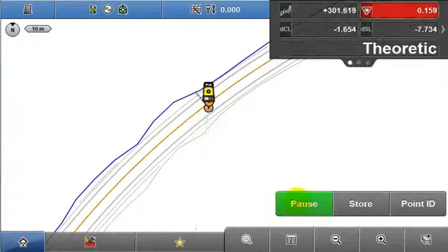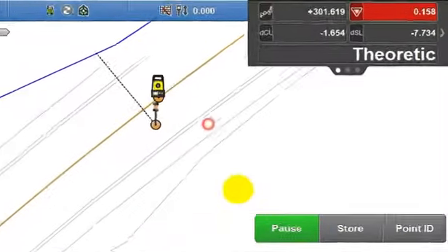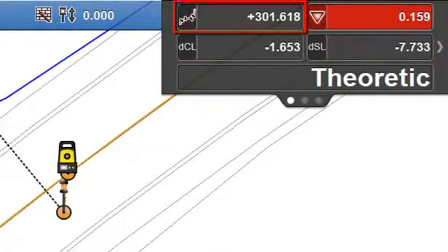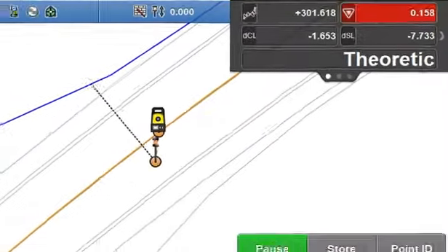Once measurements are activated, positional data relative to the selected string line at the current chainage is displayed in the info panel. For example, chainage and cut and fill are displayed here on the top line. This info panel can be configured as per each application for iCONsite.